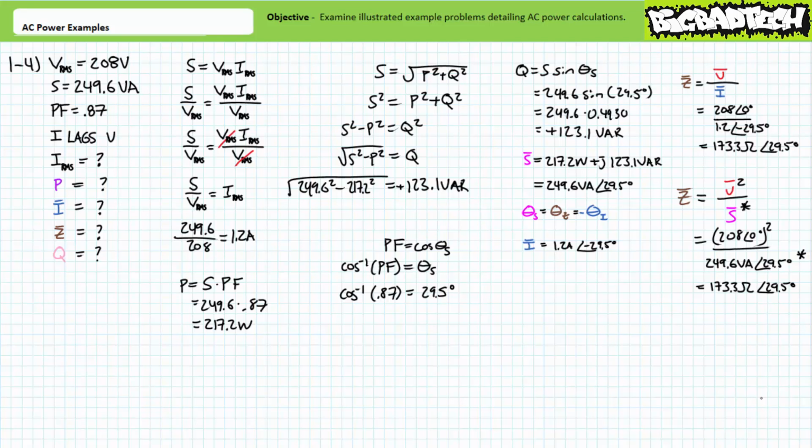This scenario is especially well suited to using a mixture of techniques, both foregoing and employing the use of complex numbers. Given current is lagging voltage, we're most likely dealing with a slightly inductive impedance, and as such, we should expect our resultant real power to be less than our apparent power magnitude and our reactive power polarity to be positive. Let's see if this is the case.